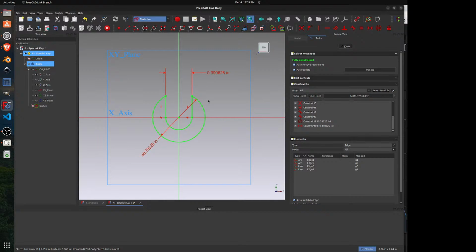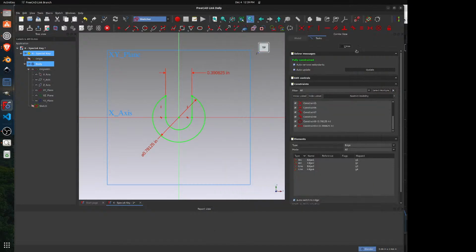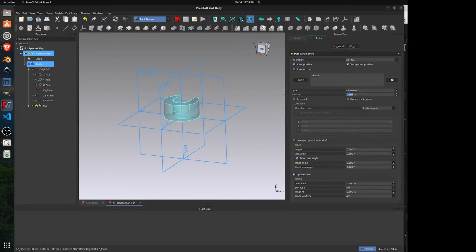Okay. And then I think it said that it was, I'm actually going to split the, go for the middle of the tolerance here. So that would be 0.12, what would that be? 0.1235 inches. So we'll close our sketch, and now we'll do an extruded pad here.